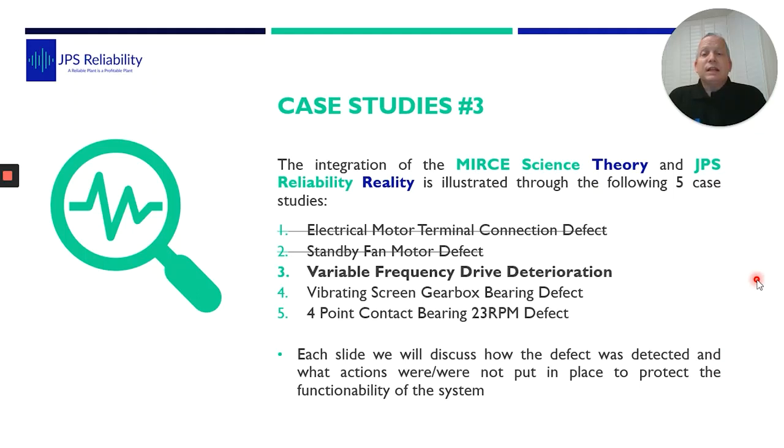There are 2 previous case studies to this, and they can be found on the link either on my blog or on the RMS website. The first case study was an electrical motor terminal defect. On this one, we highlighted using additional technologies, and is where vibration analysis detected a poor connection. The second case study was on a standby fan motor, highlighting the need for correct storage of assets and rotation of assets, as a false brinelling defect.